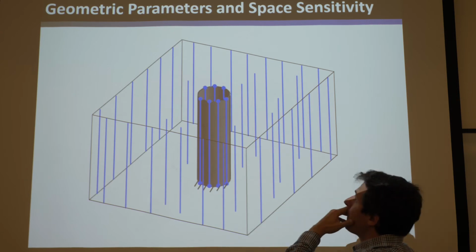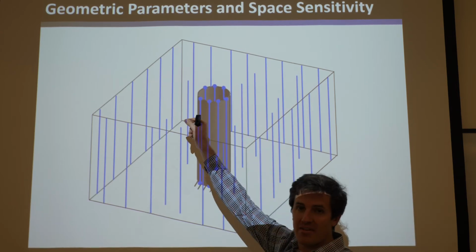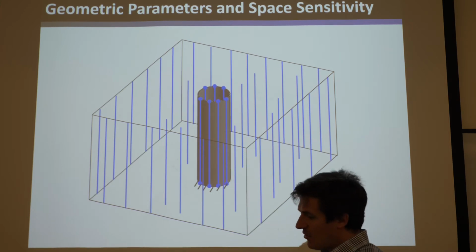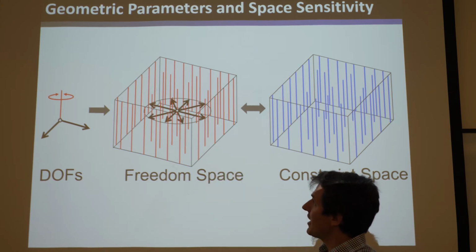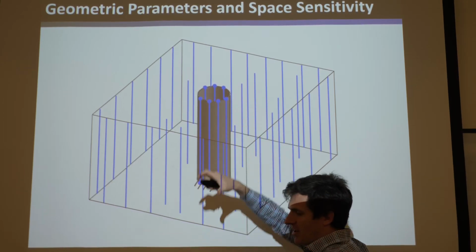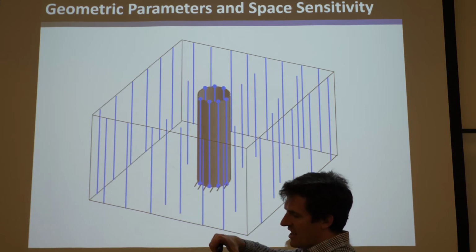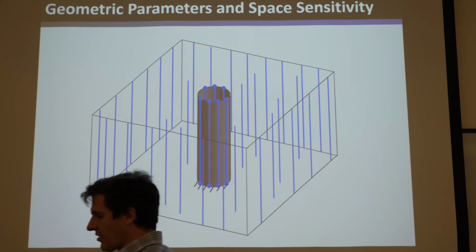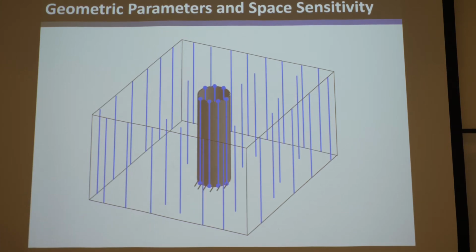Okay. Now, of course, the thinness of this has to be infinitely thin, which is, of course, impossible. But if it's super, super thin, it will mimic that constraint space, and therefore will achieve this freedom space. Okay? And that might be not terribly intuitive, but trust me, if you CAD this and put two giant blocks sandwich it on there, the first three mode shapes will be the two translations and the rotation down its axis. Okay? And then the fourth motion will be a mode shape associated with a natural frequency that may not be much larger than the third, but will definitely be in that order. Okay? And again, you could change the order of those and do fancy, disturbing things by changing the shape of those stages without touching even the element, which is, again, why I don't like definition degrees of freedom from a modal analysis standpoint. But it's still useful.